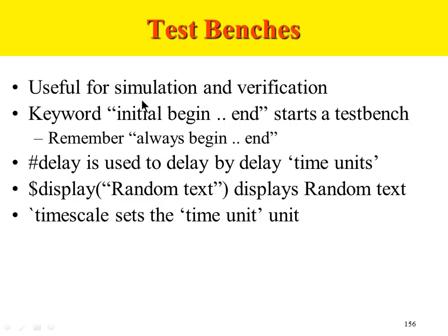Test benches are useful for simulation and verification. The test bench module that you're going to write will never be synthesized. If you're working on FPGA or ASIC, the test bench, or the testing environment, will never go on the chip. It's only the design that will go on the chip. A test bench is a testing environment used for verification purposes at the simulation or software verification level.